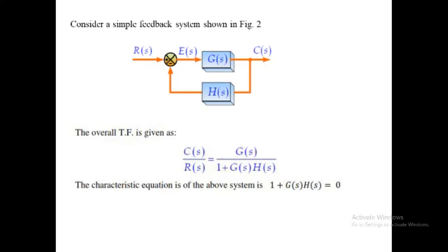Let us take one example. The given characteristic equation is A(S) = S^6 + 4S^5 + 3S^4 - 2S^3 + S^2 + 4S + 4. Is the system described by this characteristic equation stable? One coefficient is -2, that is negative, and therefore the system does not satisfy the necessary condition of stability.